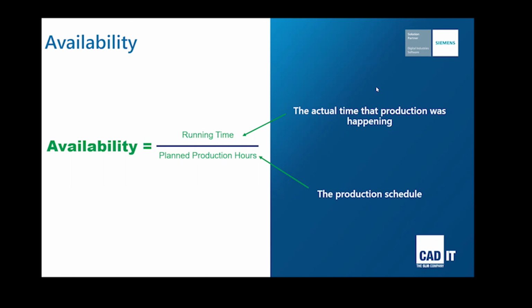They're all fine, but an OEE measure should use all the time that is planned to be available. Therefore, events like planned maintenance and calibration activities on the equipment should be removed from the value representing the production schedule.